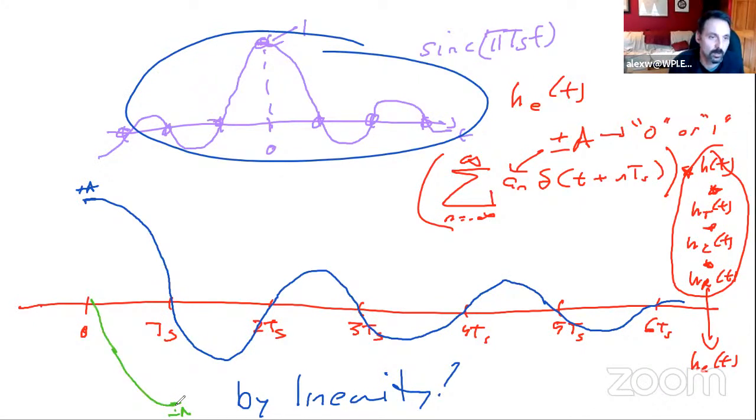There's a zero crossing. Oh, that's so important. So just quick FYI, look at this. At 0, it has a non-zero value of A. And every other sinc pulse I'm going to draw is going to go through the zero crossing. So theoretically, only A is going to be registered, not A plus other stuff from other symbols. No ISI. So it's beautiful. Let's go back to this thing.